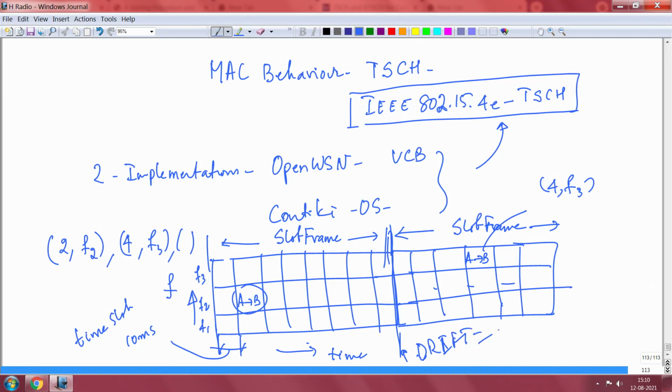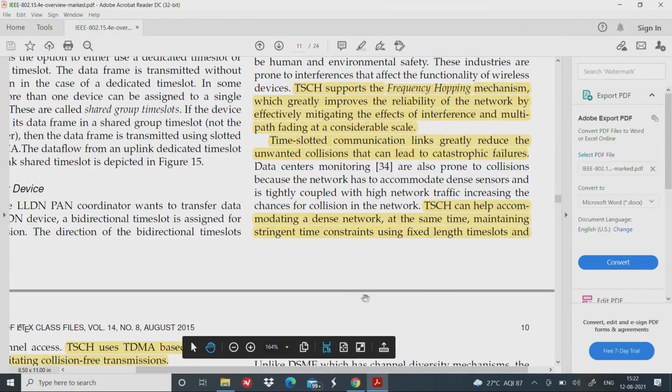drift is practically equal to 0, which is not possible given the kind of components that we are talking of, crystal oscillators and so on. It is not going to work that it will not drift, but that is the challenge. You must have a way to compensate the drift. First you should evaluate the drift and then compensate the drift, and ensure that systems in fact come exactly at the same time for communication. That is essentially what you should do, otherwise industrial networks where deterministic latencies are required will not work.